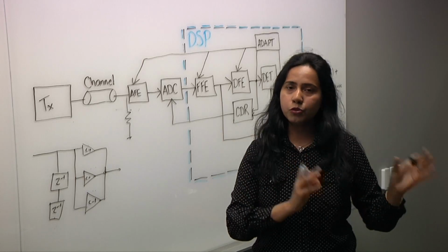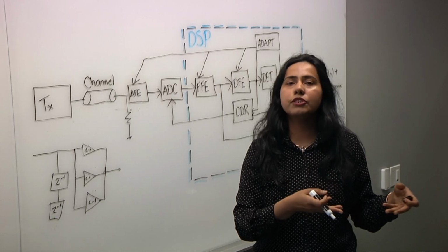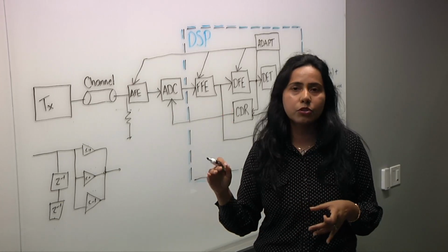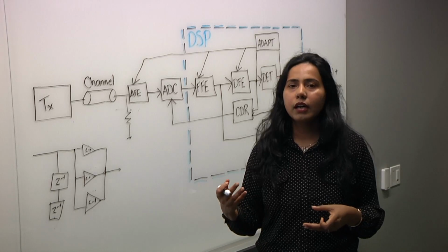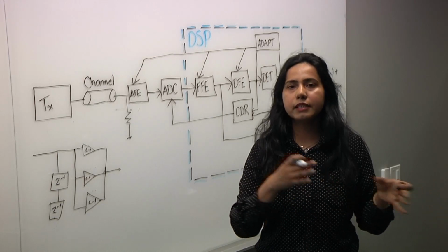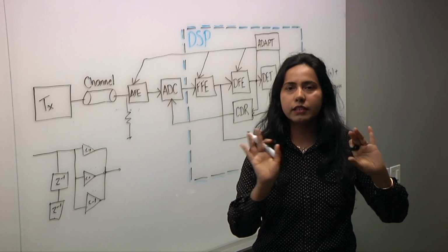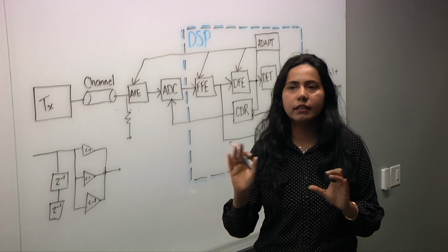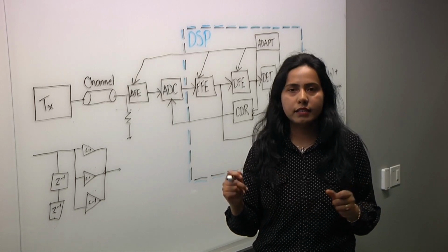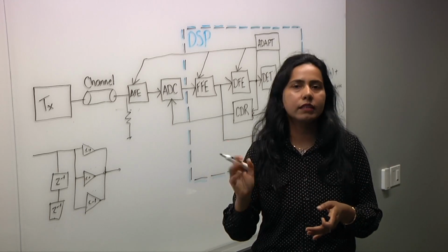And then you also have to use advanced tools like ANSYS and HFSS simulation, and make sure of the signal integrity as well as power integrity. You might have a lot of power domains in here. I want to optimize power. So for example, PCIe previously had power management, and now it has the L0P states where you can dynamically shut down some of the lanes and still maintain the traffic in mission mode. So for all of these power modes, you can perform the power integrity simulation and make sure that your package, PCB and SoC are consistently meeting the spec.